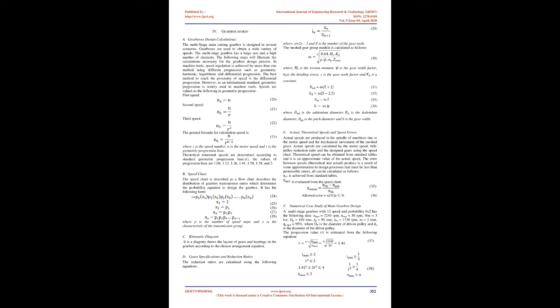Modification number 4 is the best stiff structure. So, the fourth modification is the versatile design against harmful vibration. The mode shapes of the milling machine and the milling machine with the modifications added to the machine column are thoroughly investigated to see how significance in structural behavior is obtained. Fig 8 shows the first mode shape of the original milling machine and the milling machine with modifications. The milling machine can safely use wide cutting conditions as the cutting speed without dangerous resonance occurring.